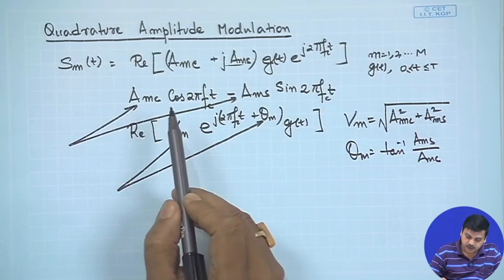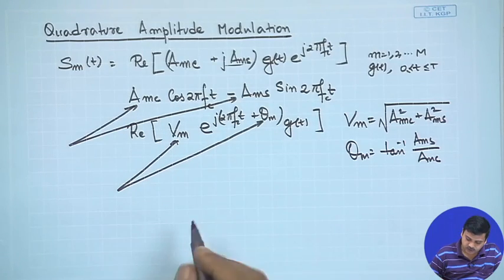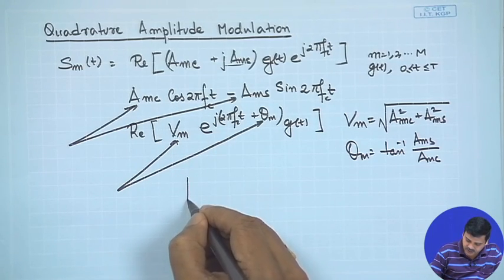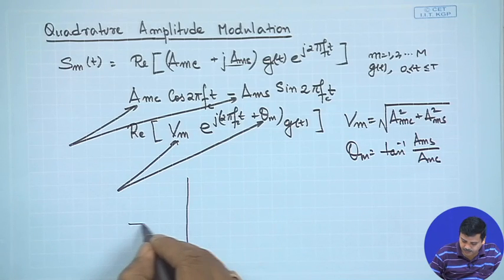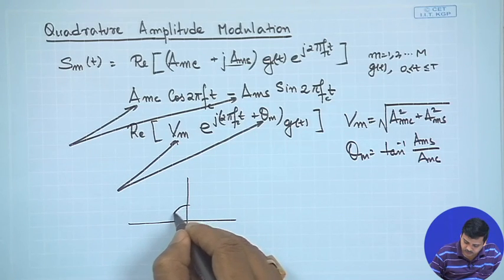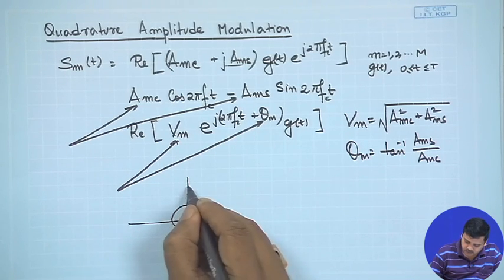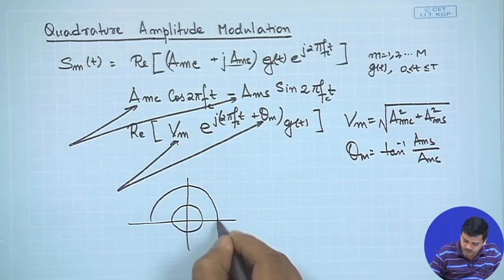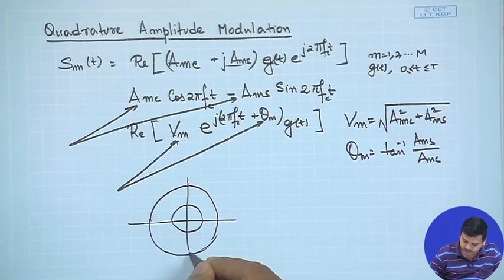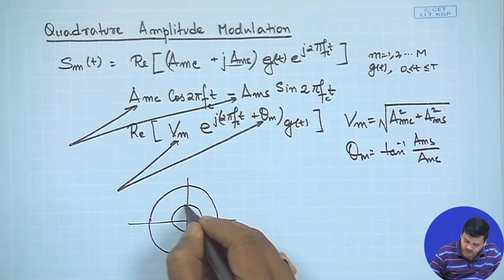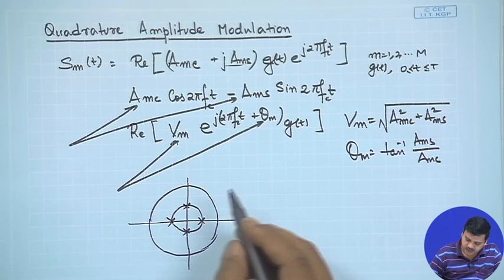So these are some of the things that we have discussed, and then we said, what would be the corresponding signal space diagram or the constellation diagram? If we combine the amplitude and phase modulations, then one could use M1 level amplitudes. As an example, we took 2 amplitude levels, and then one could use 4 phases.